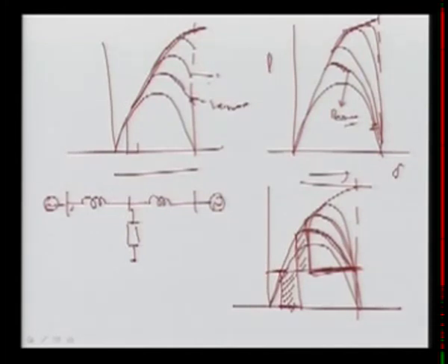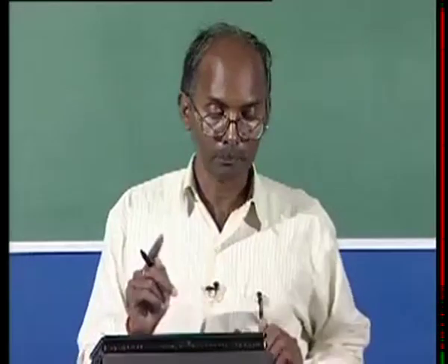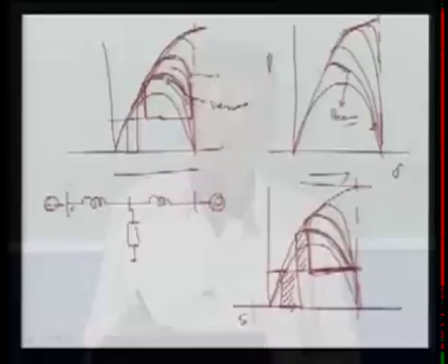Now the same, if you will see here, what we are going to do. Now you can see this value is now hitting, and it is not 0 here, we are getting this characteristic more. Now if it is more, it is this. So this is not going to be 0, earlier it was going to be 0 here, so we are having more margin. So we can say the STATCOMs are better in terms of dynamic performance than your SVC, but the STATCOMs are expensive compared to your SVC, and that's why the SVC is very popular and very simple also.